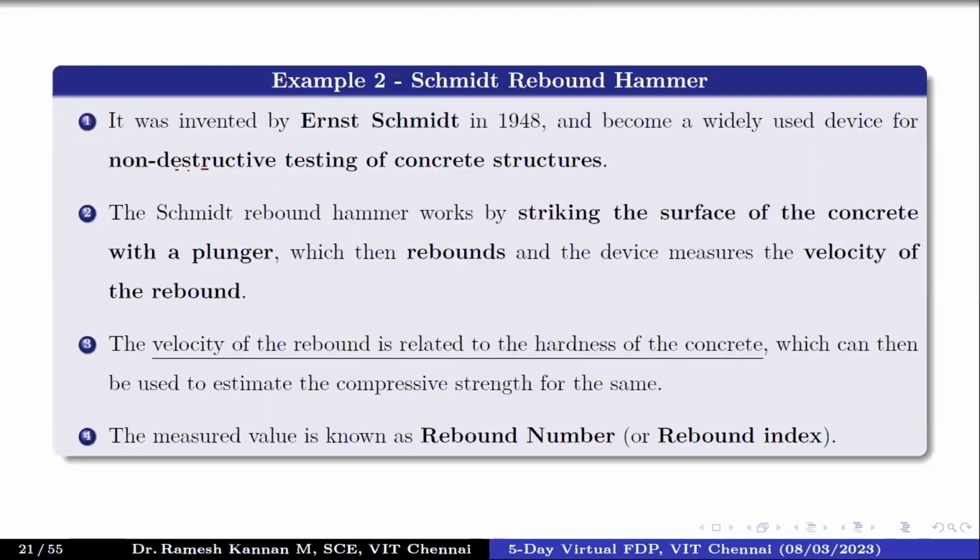We call it the Schmidt rebound hammer, and it is still used till now. It comes in different varieties nowadays, like digital portable devices. But it's still one of the important non-destructive tests for a quicker estimate of the compressive strength. It may not give you a more accurate value, but it will give you quite a good picture of the existing structure.